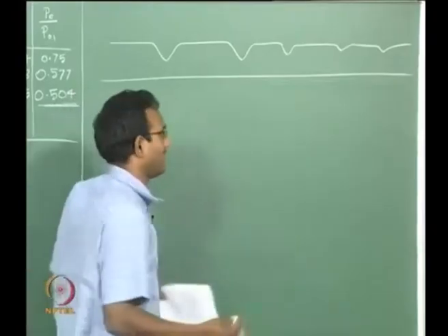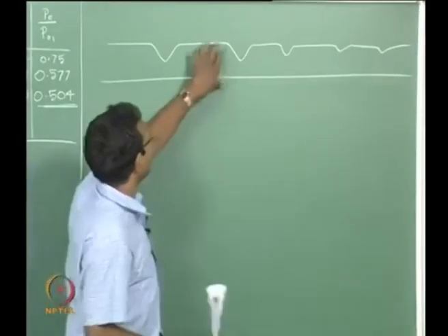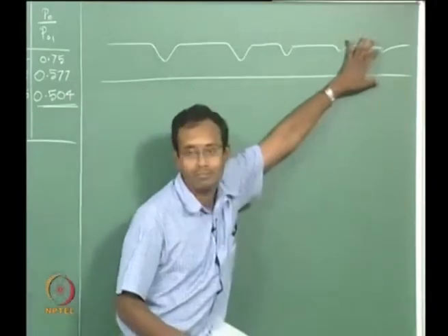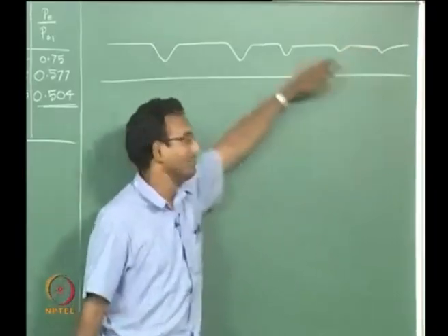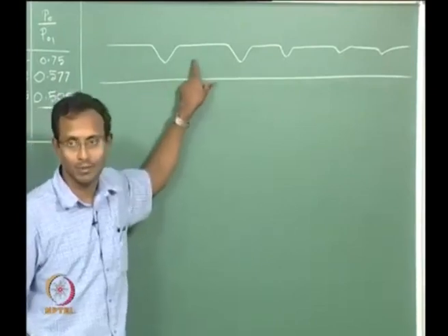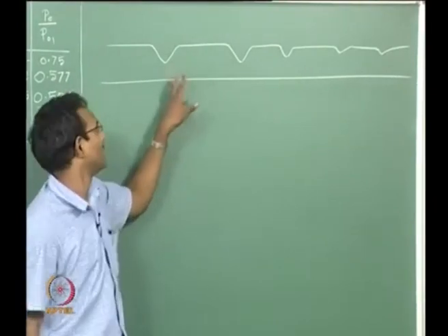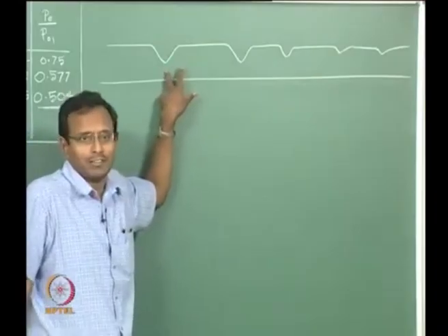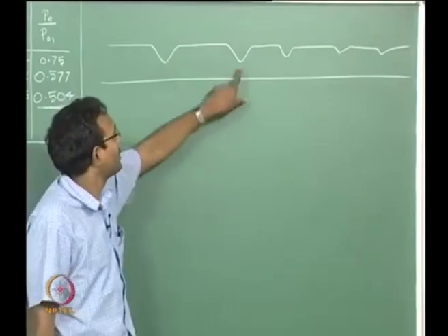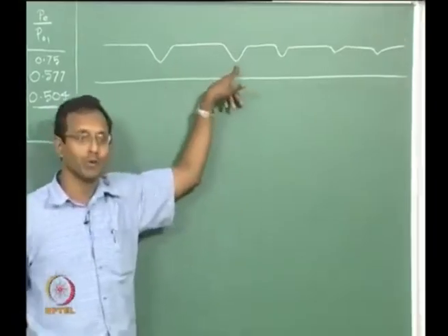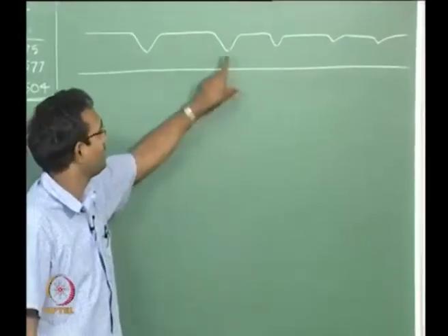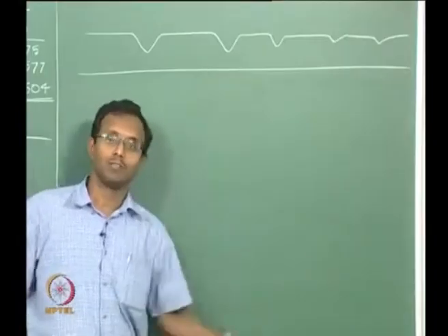Okay. Let us say initially I did not have any of these bumps, I just had one CD nozzle and then a straight line duct. I set some pressure, a P naught, and I know it became supersonic after this point. Or, I just worry about choking, it choked definitely. I went below P critical 1 for this throat, it choked. After that, if I wanted to choke again, what should I do? I want this choking to be present and this choking to be present. What should I do?